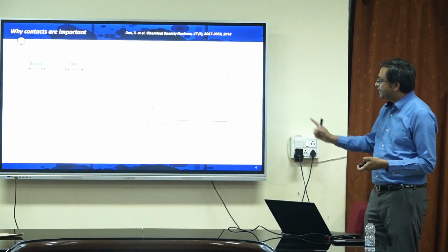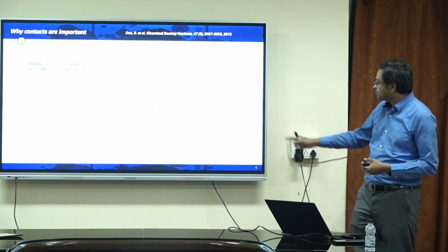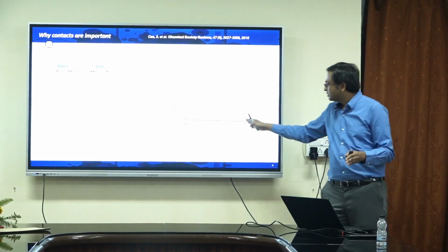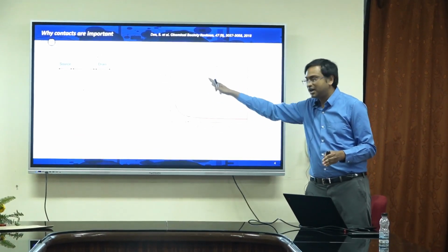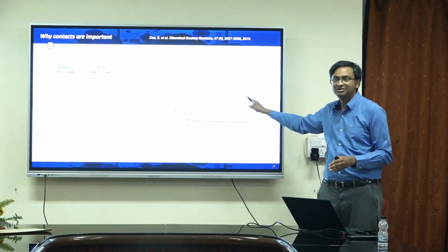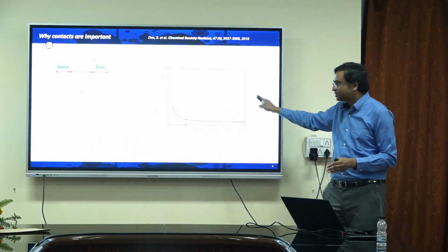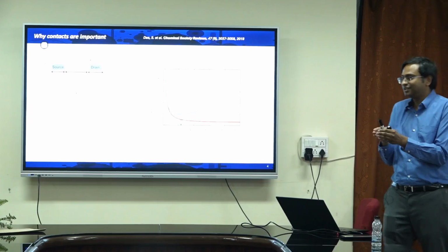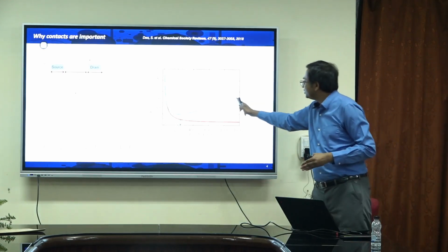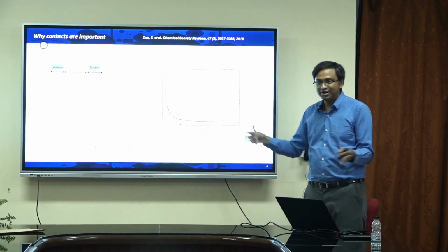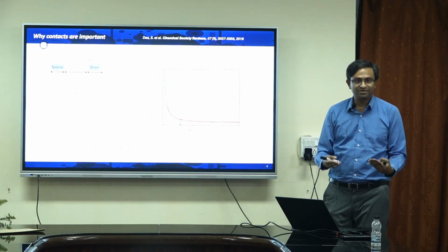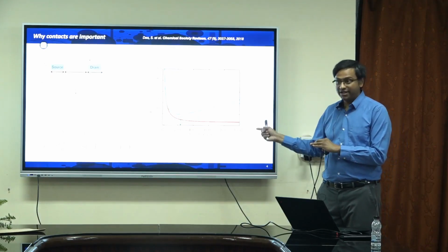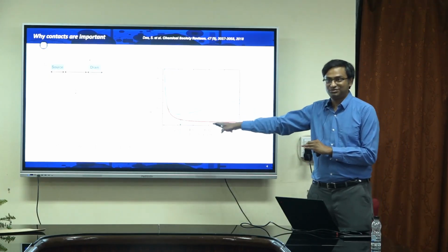Therefore, if I now wanted to plot the total resistance, you see the channel resistance goes down to 0 as my length of the device becomes smaller, but contact resistance becomes large. The total resistance is a non-monotonic trend, correct? So, it goes down, but this is where we are interested. Today, when we are making nanoscale devices, we are not in this regime where everything is nice and clean, I reduce my device size, I get better performance. Now, if I make the device too small, my contacts become dominant and it dominates over everything, correct?